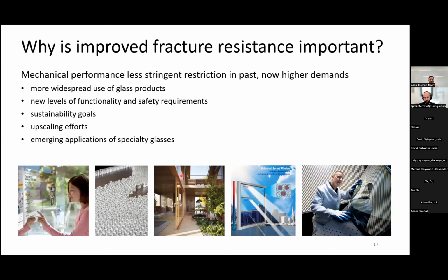And the most efficient way of doing that is to make thinner glasses than those that we use today. So that affects the whole chain, because glass production is a very CO2-intensive process, with high temperatures and, in many cases, carbonated raw materials. So if we can make glasses stronger, if we can make them tougher, that is really the key step to making them thinner, and therefore reduce cost or the CO2 footprint of the production, of the transportation, and essentially of all the steps that contribute to that footprint.